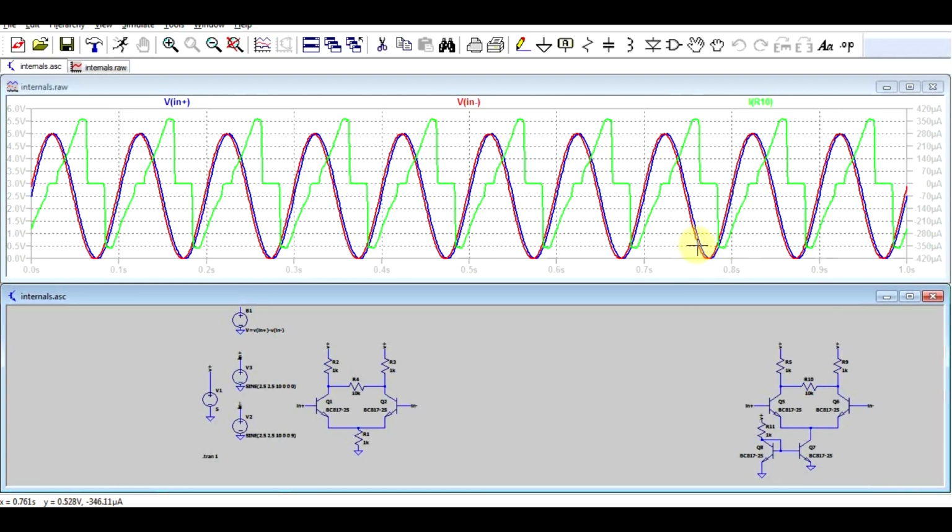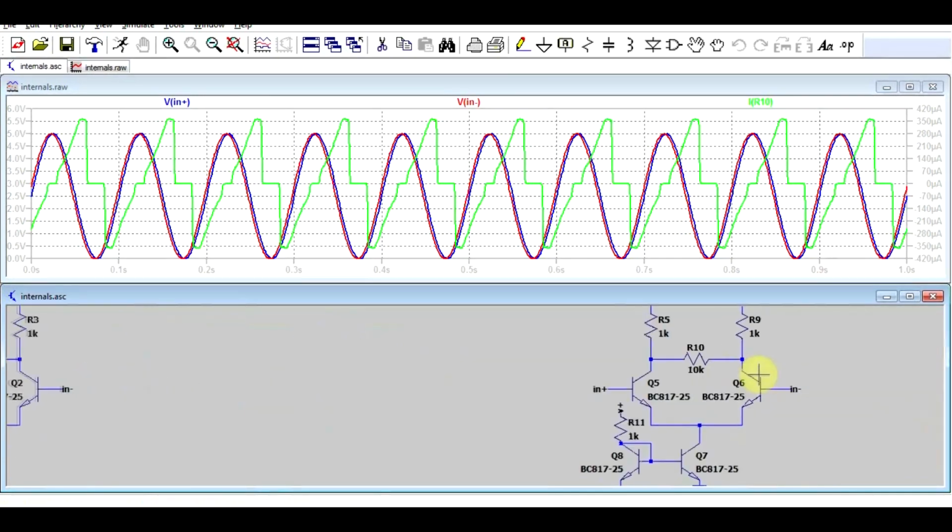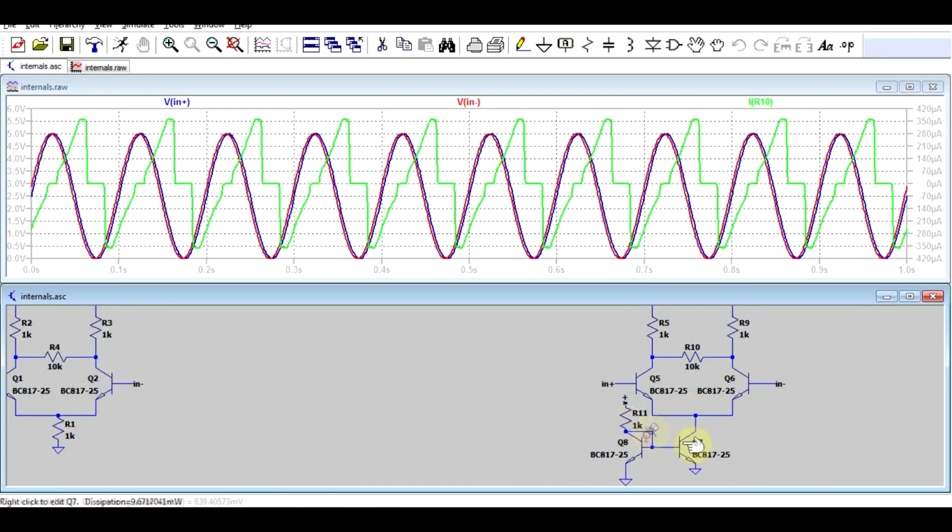So what's going on when the two voltages are low? Well, to be able to drive the comparator, we need to be able to drive the transistors in the comparator. So let's look at these two transistors down below. To drive transistor Q8, we are supplying it from our positive supply, 5V, never changing, everything is fine, no problem with it. To drive Q7, we've got signal from the same line, so we don't really have any problems with it, or any limitations. Now we do have a limitation in the collector emitter voltage. Depending on the type of transistor, this needs to be above or around 0.1, 0.2 volts, since that is the collector emitter saturation voltage. So the lowest voltage you can get in this point is around 0.1, 0.2 volts.